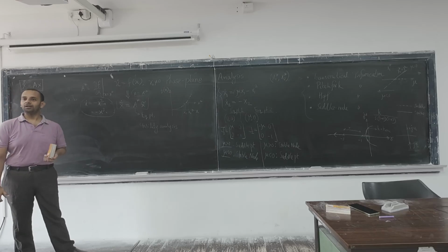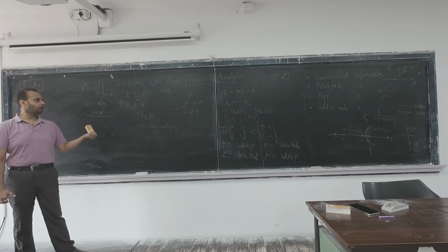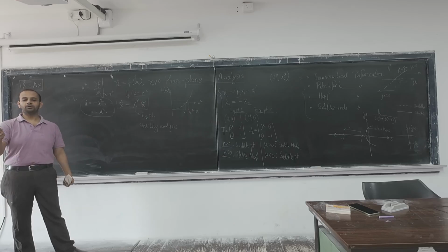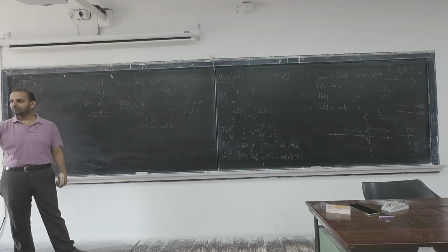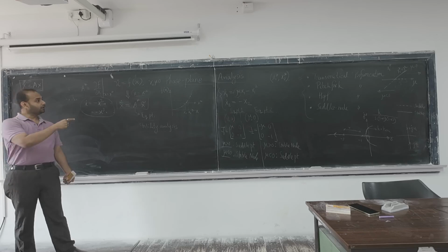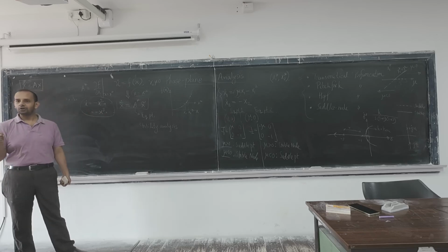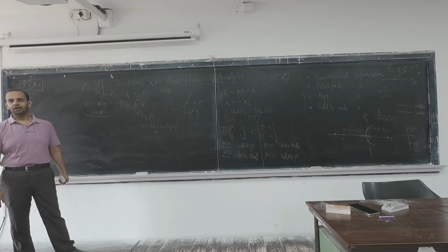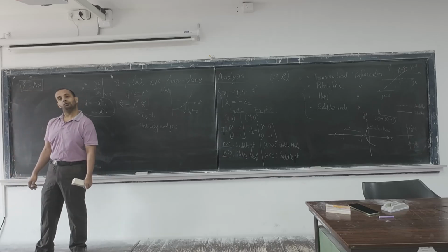So it will of course be local in nature. At the same time, depending upon parameter uncertainty, disturbances, or a change in operating conditions, the operating point will shift. And as you know, it is a local model, so if the operating point changes, the A star, or the Jacobian, will also change. But the controller is a fixed-structure controller, designed with respect to a particular A star. Then of course the performance will degrade, and that is why we go for a robust controller.